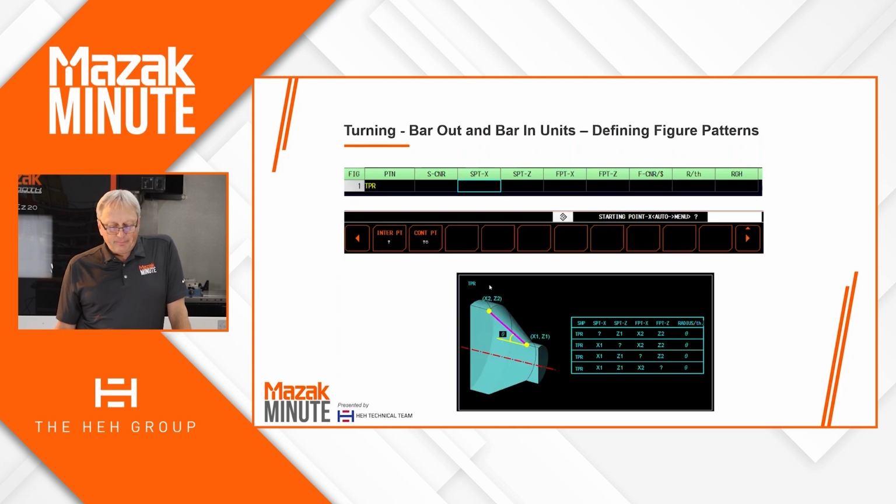On a taper line, you have the ability here to have start point X, start point Z, because there's a beginning and an end to it. It could be at two different diameters or two different positions in Z. If I move my cursor there, notice the soft keys down below. It's going to say question mark, and that's basically our unknown. It's for an intersect point as well as continuous point, which would be like it being tangent.